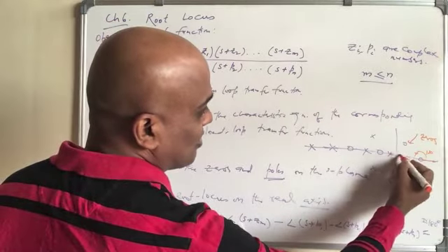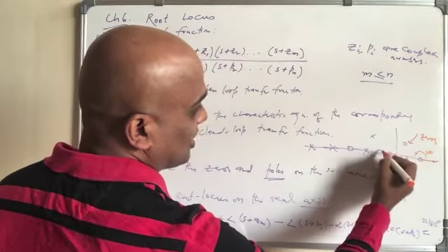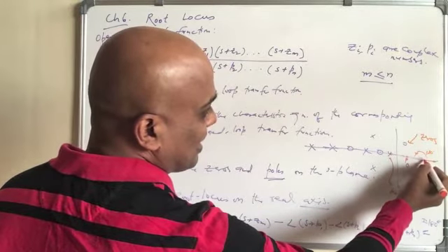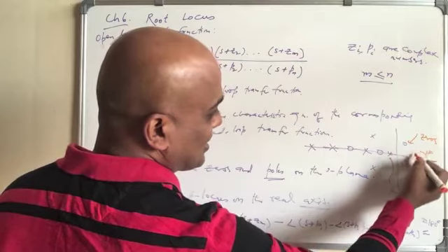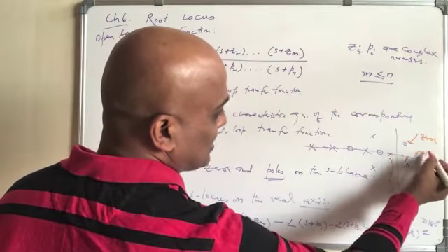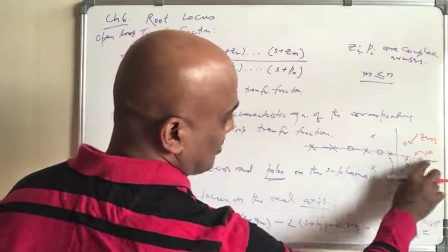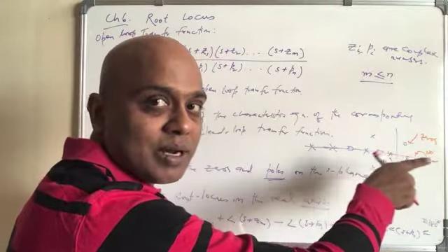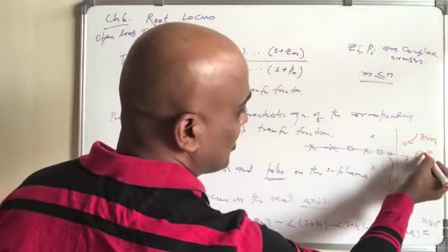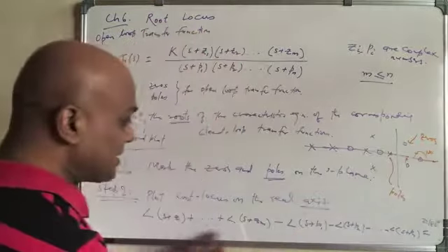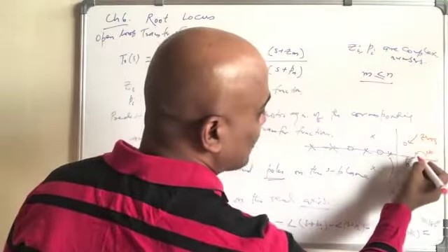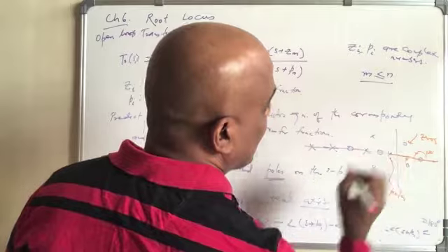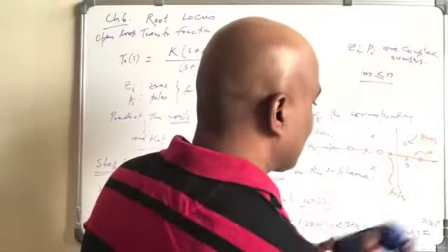If you connect from here to here, the angle is 0 only. Connect from here to here, angle is 0. Only this one has 180 degree, because you have to measure it from the horizontal line, which is going right, to the positive x direction. So here 180 degree. So what you get? In this case, you get 180 degree, meaning that point here to here are basing on the root locus.